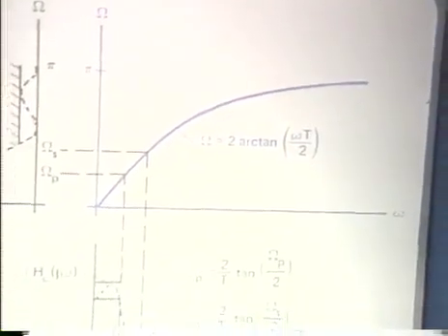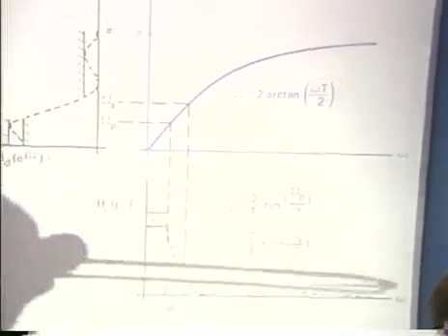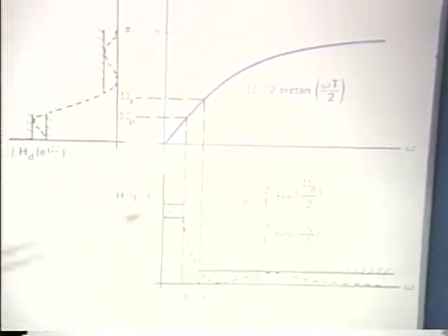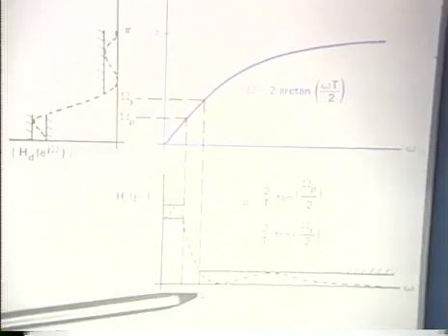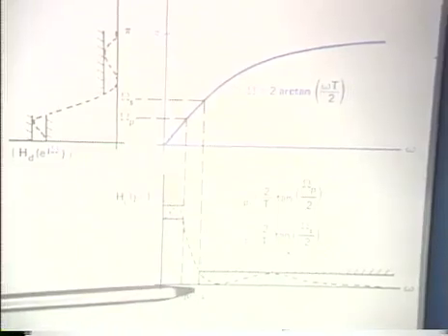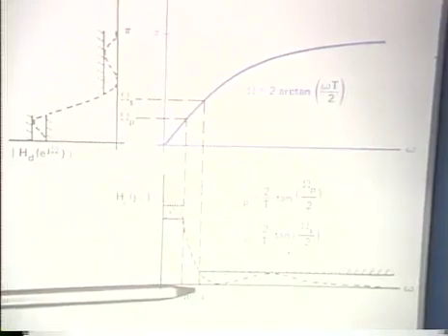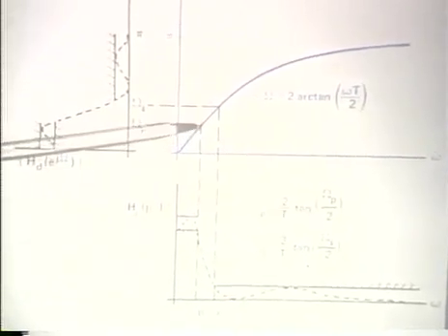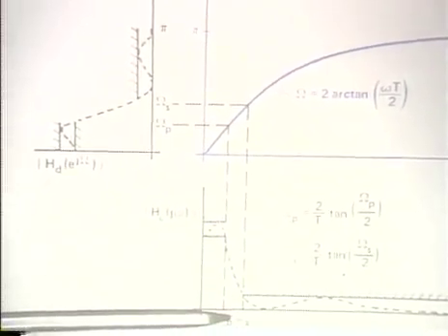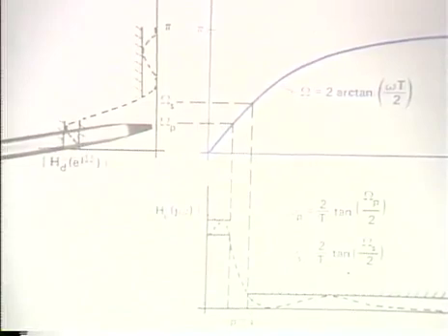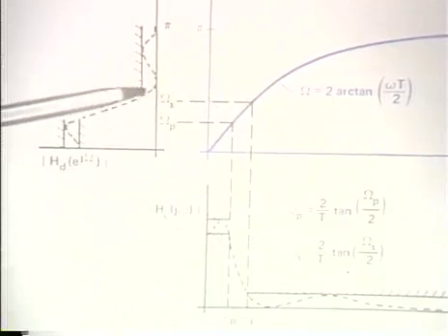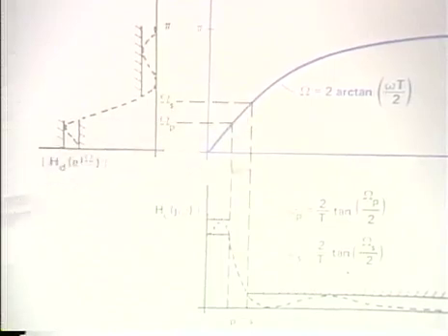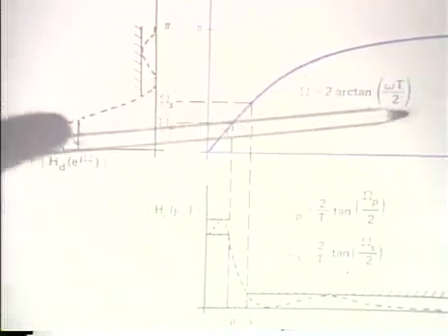So let's suppose that the continuous time frequency response looks as I've shown here, with a passband cutoff frequency and a stopband cutoff frequency. If this were mapped through the bilinear transformation to a discrete time filter, then this cutoff frequency would fall over here, which is related through this curve, and this cutoff frequency, the stopband edge, would be here, again reflected through this curve.